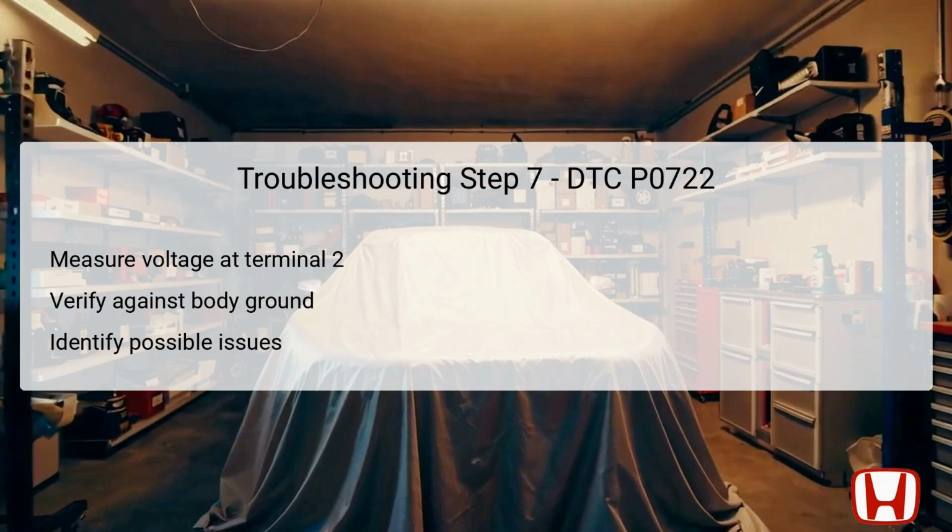if the voltage is absent or outside of expected parameters, there could be an internal fault within the sensor or failure in the circuit wiring. This step is vital for determining whether the sensor or its circuit requires repair or replacement. Mastering this diagnostic approach ensures comprehensive evaluation of component functionality.